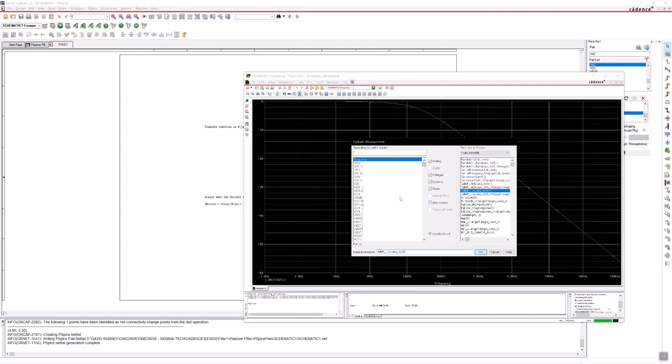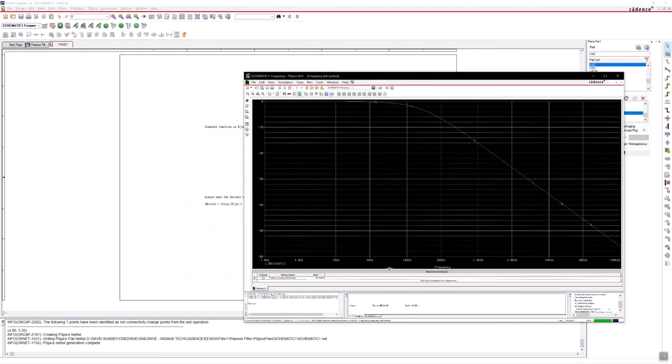I'll just go ahead and do it right now to show you what the error is. If I just simply put V out in here, it actually, oh, in this case it does. Sometimes you get an error here. Low pass filter, this is actually correct. This is 158.7 hertz. Sometimes you need to convert it though to decibel rating.